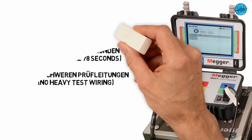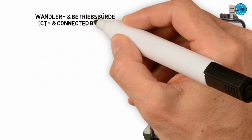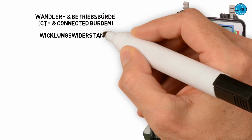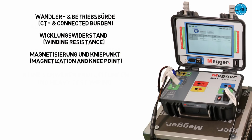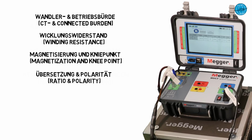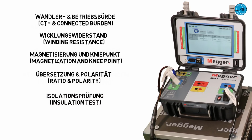The following tests on current transformers are generally possible: the measurement of the current transformer and the connected burden, determination of the winding resistance, measuring the magnetization characteristic and determining the knee point voltage, measurement of the ratio and the polarity, and the 1 kV DC insulation test.